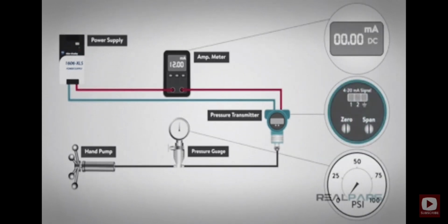If we have an analog transmitter, we must adjust 0 and span to reduce the measurement error. With an analog transmitter, there is a 0 and span adjustment on the transmitter itself. 0 adjustment is made to move the output to exactly 4 milliamps when a 0% process measurement is applied to the transmitter. And the span adjustment is made to move the output to exactly 20 milliamps when a 100% process measurement is applied.